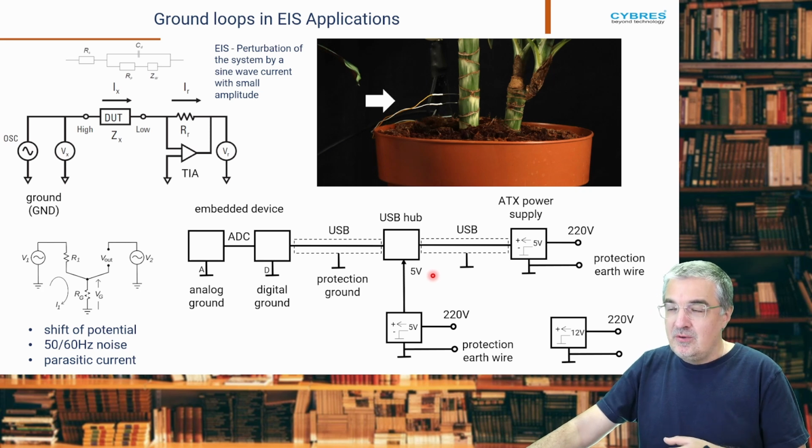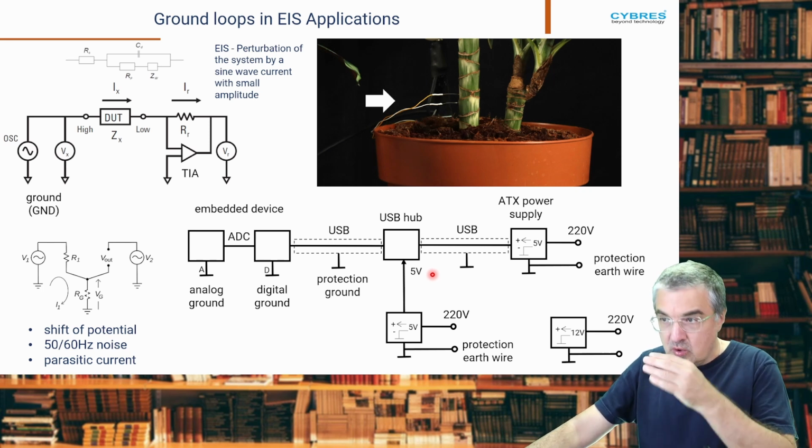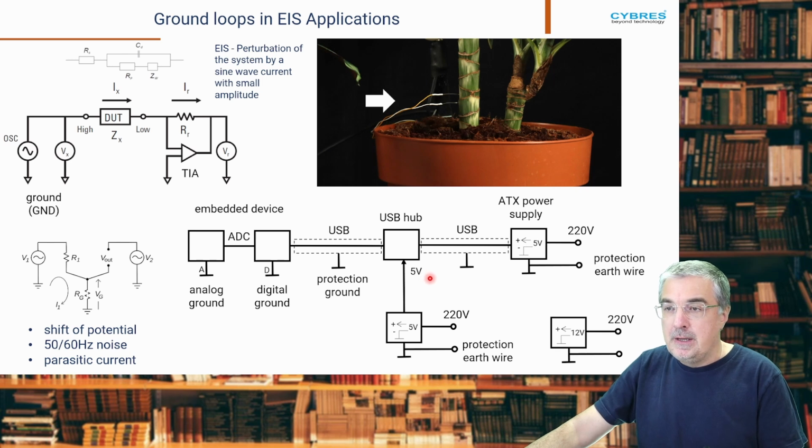In some cases, you see a reboot of devices because of this spike of potential. So if you have any of these appearances, stop the measurement, disassemble your network, and try to debug it, and remove the power supply that has these undesired effects.